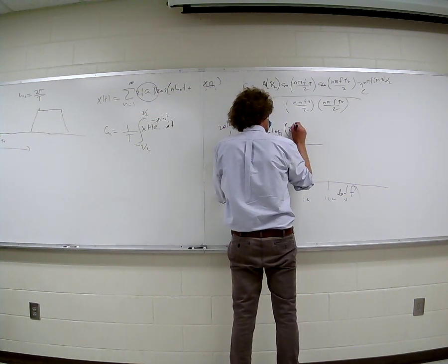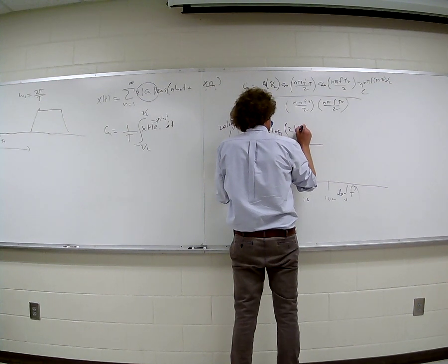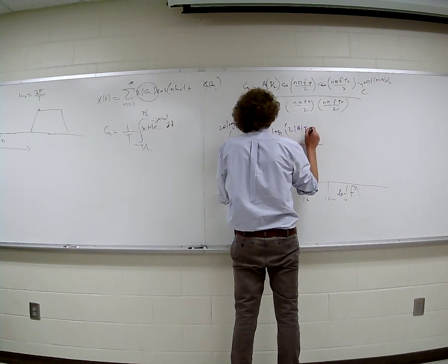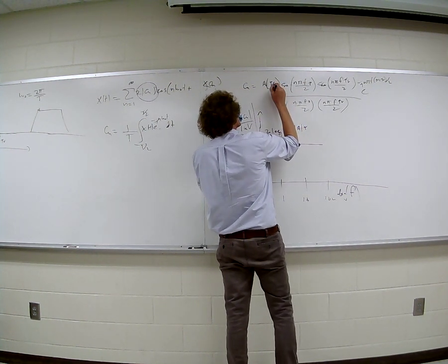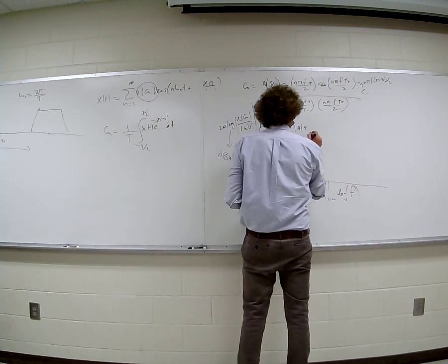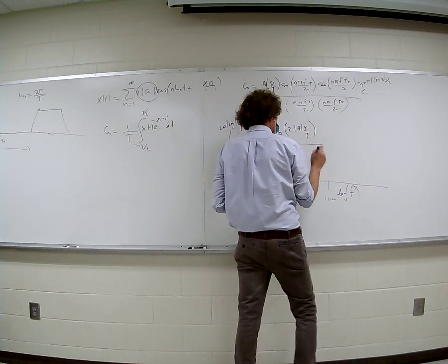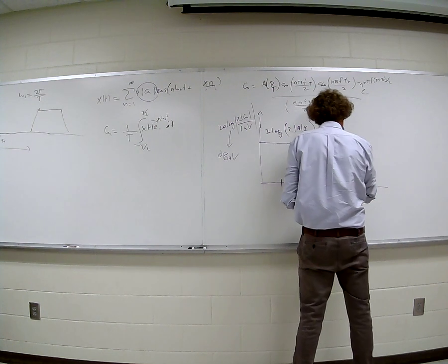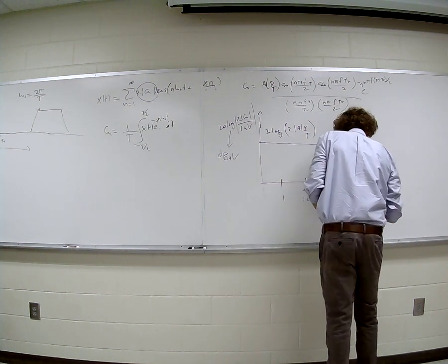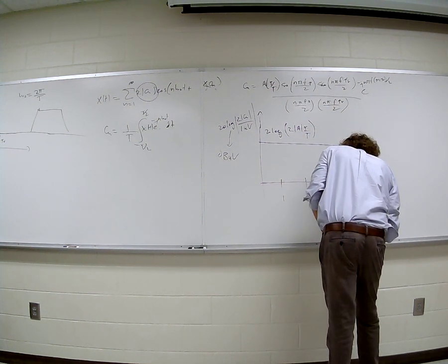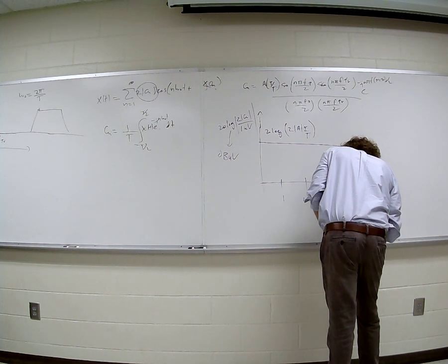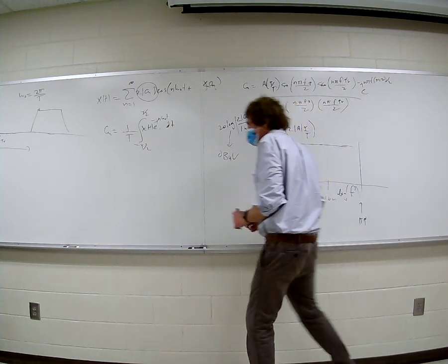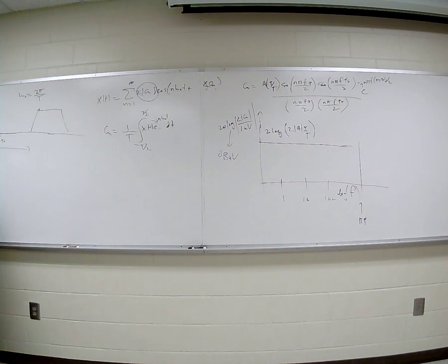So it's going to be 2 times the magnitude of A tau over T, right there. That's where it starts, and it's going to stay there until I hit the first break frequency. That frequency will be 1 over pi times tau, or 1 over pi times tau rise. Let me get that down there. There's the laser.